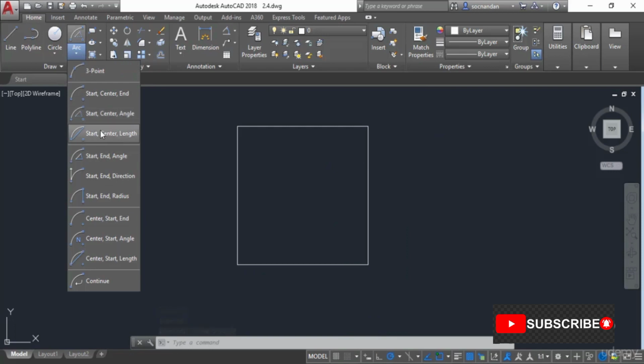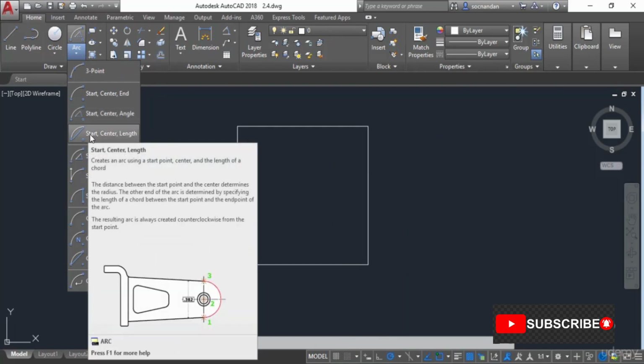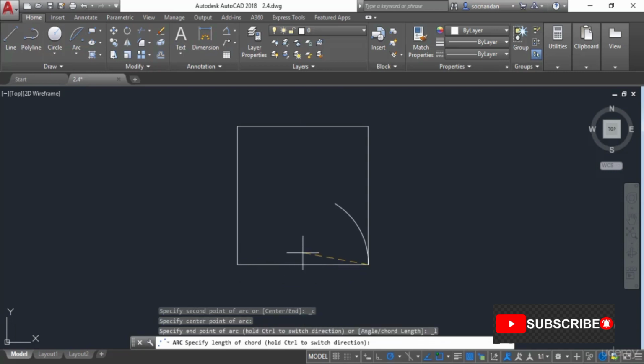In a similar way, you can create an arc with a chord length. Here also we need to enter the start point, then the center point, and then the chord length. So let's select it and click at the start point. And now the center point, which you can select at this point or any other point. Let's click here, that will be the center point. And now you need to enter the chord length, and in this case the maximum chord length can be equal to the diameter, and you cannot make a chord which is longer than the diameter obviously, and depending upon the chord length the arc will be made.